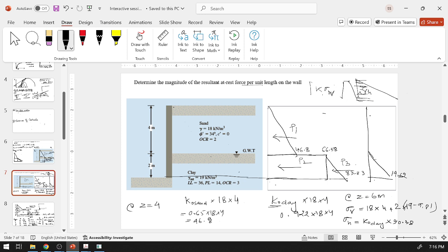If we take the sigma vertical as total load, we will be multiplying even the gamma w, even the pore water pressure, with a factor of K, which is not correct. You understand? That is why we don't take it with the total pressure, because if we take total pressure here, we will be multiplying the U component with the earth pressure coefficient. So we have to consider the water pressure. I'm not saying that we don't consider the water pressure. We don't consider it in the lateral pressure. We have to calculate it separately.